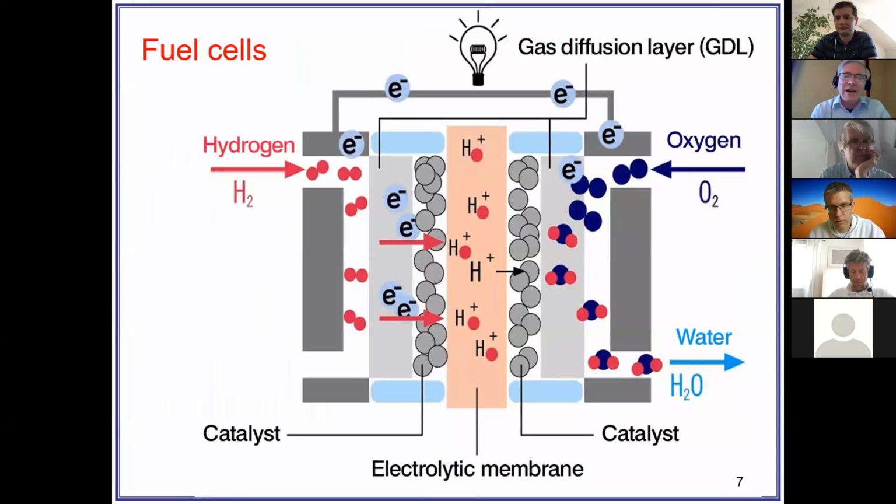The second thing is actually porous materials, flowing porous media, is not in any sense confined to geological applications. Okay, so here is just a cartoon of a fuel cell. It's a way of taking hydrogen and oxygen and generating electricity. So if we're moving towards a low carbon society, fuel cells, batteries are obviously big things. Here, what you have, rather interestingly, is what's called a gas diffusion layer. You need the gas, say the hydrogen, to move through a porous medium. Here at the electrodes, you produce water and you want the water to escape.